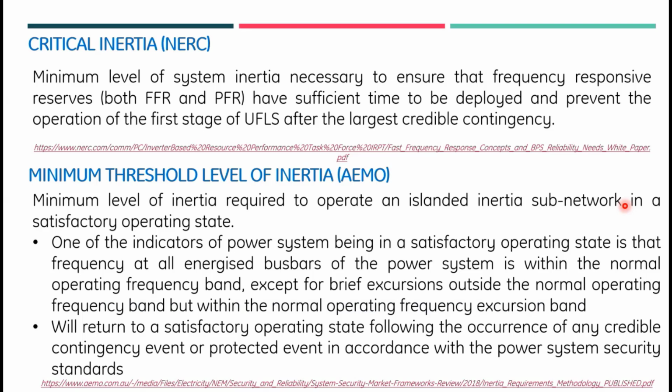So we have the minimum inertia concept in the Indian system. Then NERC in the USA has a critical inertia concept, and the Australian Energy Market Operator has a minimum threshold level of inertia concept. So these are coming in all the places because of the high integration. These were not the earlier issues. Now it is coming into it.